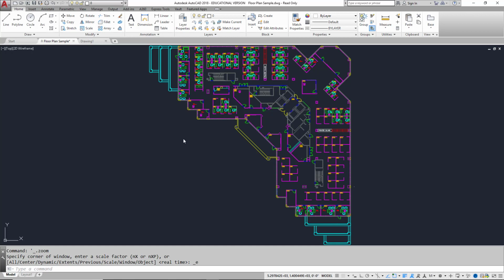Layers can reduce the visual complexity of a drawing and improve display performance by hiding information that you don't need to see at the moment. Before you start a drawing, you should create a set of layers that are useful to your work. In a house plan, you might create layers for the foundation, floor plan, doors, fixtures, electrical, and so on. With layers, you can associate objects by their function or location, display or hide all related objects in a single operation, and enforce line type, color, and other property standards for each layer.